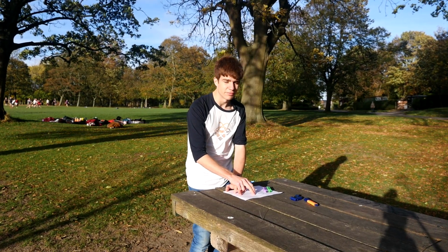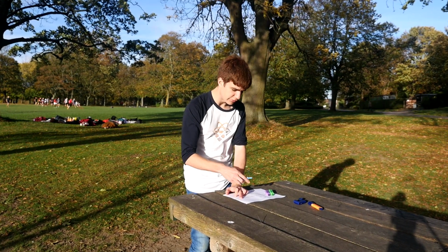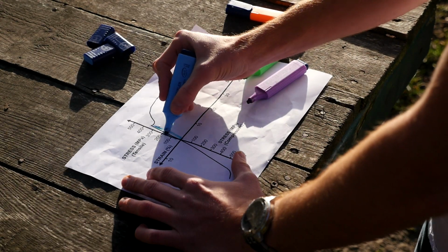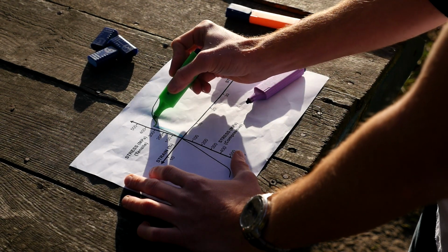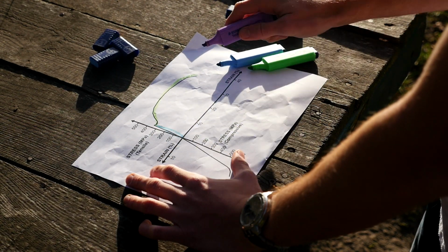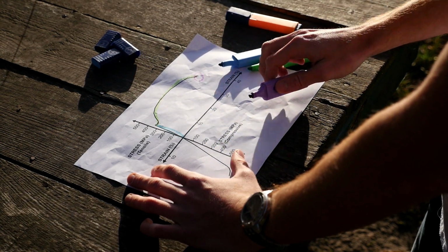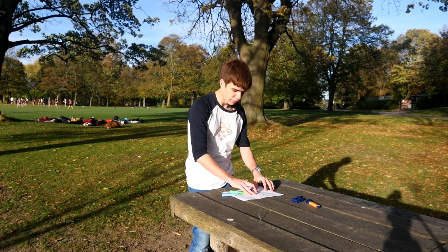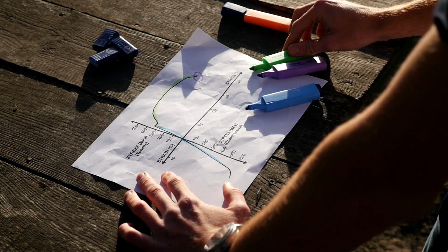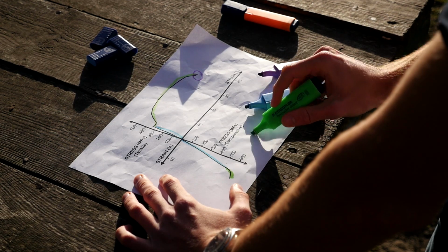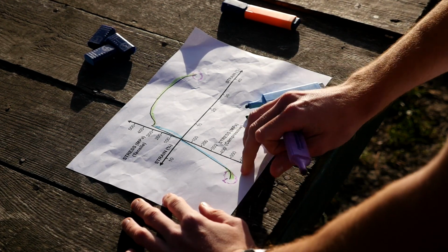Here is the tension bit of the curve. You can see the key regions. Here we have linear, elastic deformation. Next, we have the curvy plastic. And finally, this endpoint is where failure occurs. We have some very similar structures for the compression section. We've got our elastic deformation, barreling, and finally breakage.